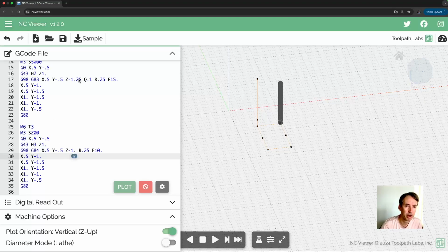It doesn't necessarily need to be a 1/4 inch deeper. But if it's a through hole, you want to drill all the way through your part so that you have plenty of chip clearance.